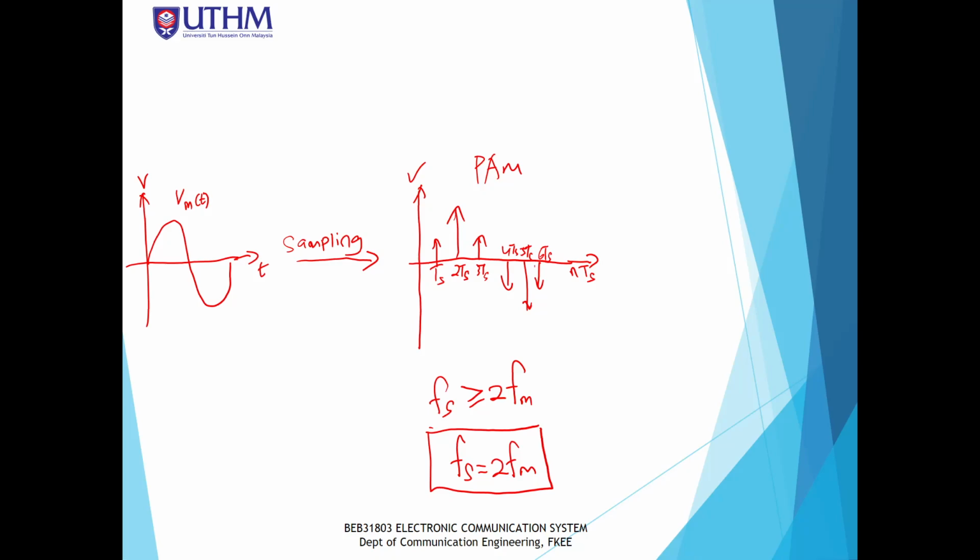But there is a drawback to a higher number of samples. There is a give and take between the sampling rate and the bandwidth requirement. If you sample a lot, you need bigger bandwidth to accommodate the sample values. After sampling, we can do the quantization.